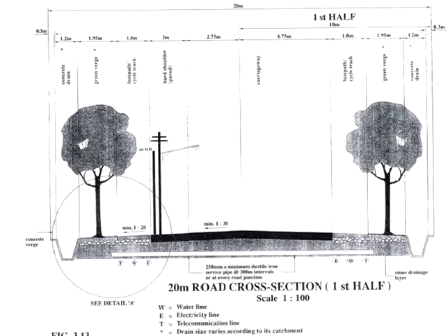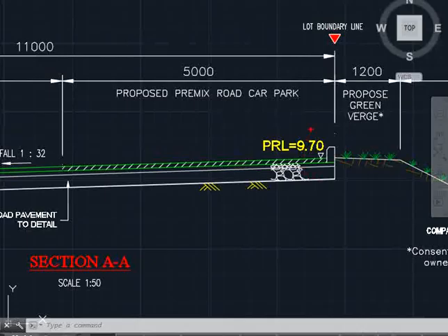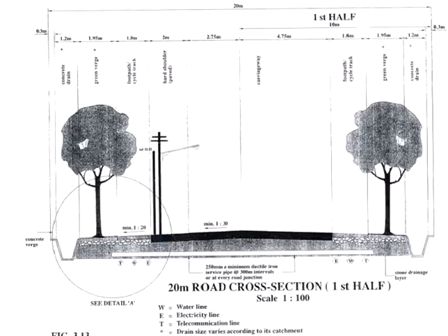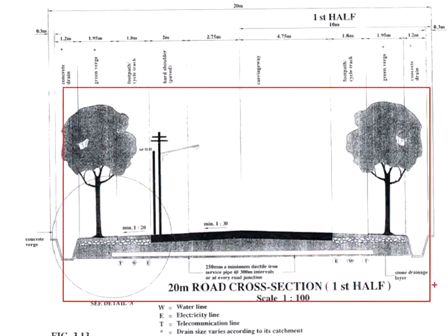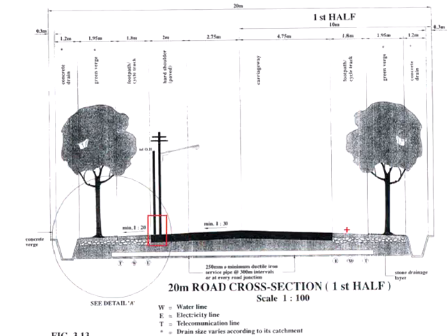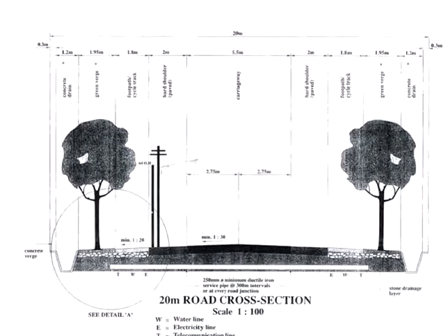Next is about the curb. The curb is normally put along the edge of the road to restrain the movement of vehicles out of the pavement. If, in accordance to the standards, no curb is required for a typical road reserve, you don't have to provide curb. The provision of curb may be on the basis of requests by the local authorities upon the submission. As a designer, you may also decide whether to have the curb in place.